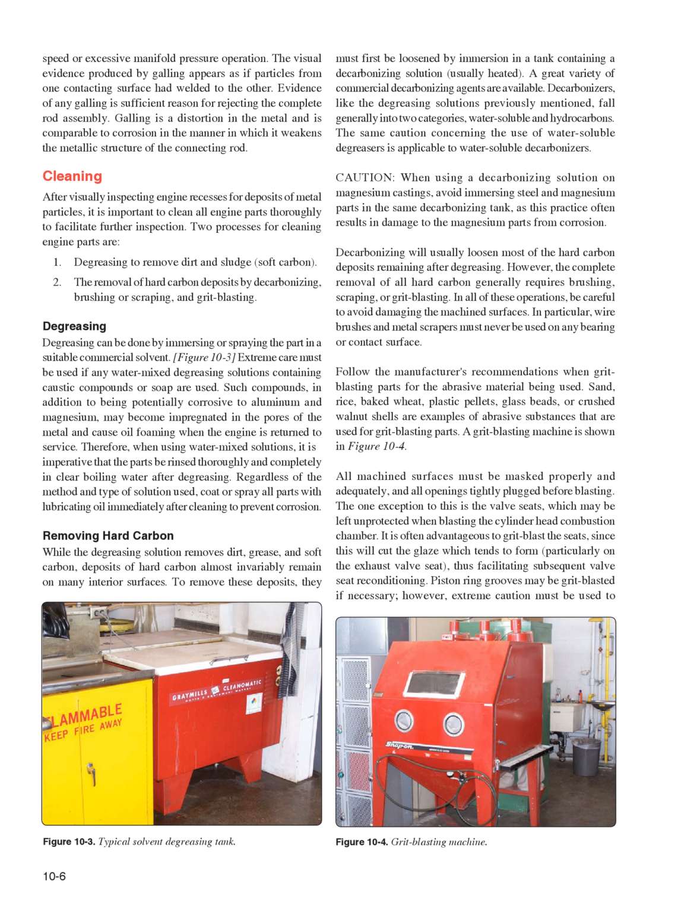Removing hard carbon. While the degreasing solution removes dirt, grease, and soft carbon, deposits of hard carbon almost invariably remain on many interior surfaces. To remove these deposits, they must first be loosened by immersion in a tank containing a decarbonizing solution, usually heated. A great variety of commercial decarbonizing agents are available. Decarbonizers, like the degreasing solutions previously mentioned, fall generally into two categories: water-soluble and hydrocarbons. The same caution concerning the use of water-soluble degreasers is applicable to water-soluble decarbonizers.